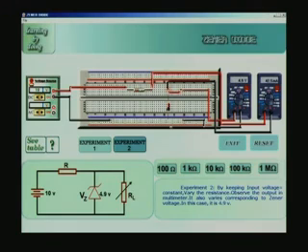The current meter is actually connected in series with the RS. It is not the load current which I am measuring. Therefore, even though I change the value of the resistors, the current is not changing here, because this is the current in series with the RS. In principle you can put a current meter in series with the load also, and then you would find the load current keeps changing depending upon the value of the resistor that I connect here.